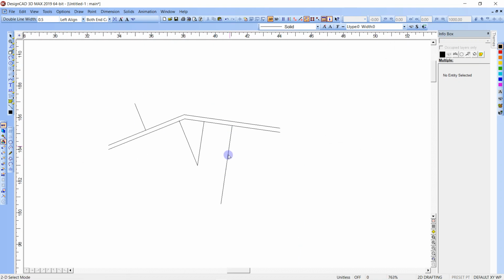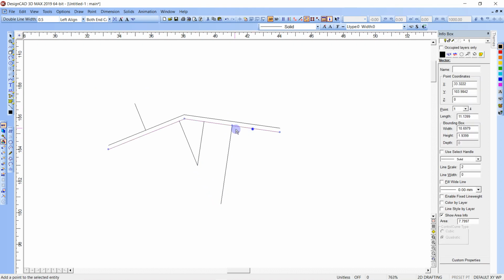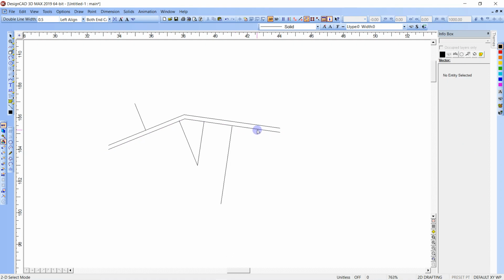It doesn't give you the option to just drag it away. So V, let's do this. I'm going to split that line there. So now this is a line segment V, Control K. I want to go perpendicular away, and I just want to drag it to, let's say, that length. I'm going to go J, A, enter, 90 degrees. It's going to go 90 degrees from this line, and I can snap there, and then all those are at 90-degree angles.